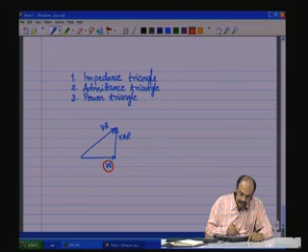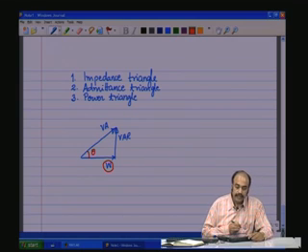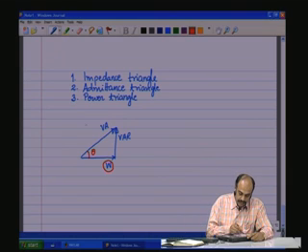This reactive power is actually put back into the mains, and this is the VA, or the resultant power, that is drawn from the mains, or the source should be rated for, and this is the power factor angle. This has very important implications, and one should understand that properly.